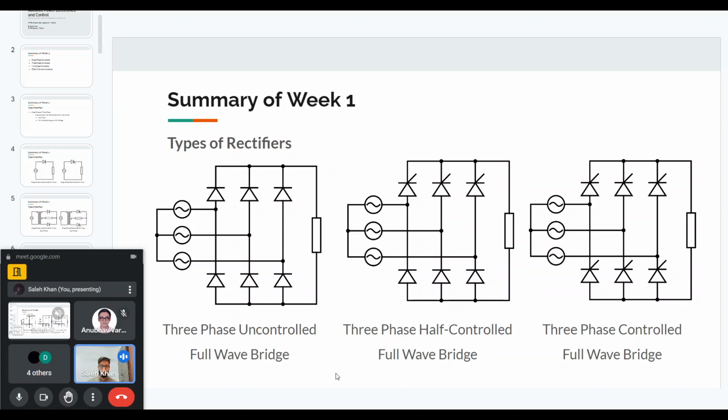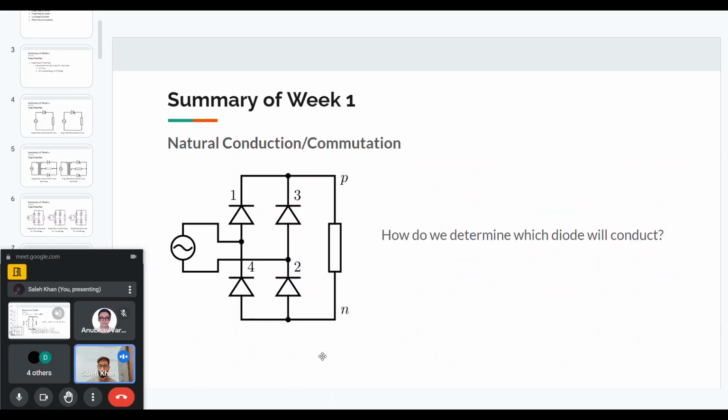And so another converter that was taught was a dual converter, which is just this converter with another of these converters connected on the other side, which allows for a negative current, and therefore we can have 4-quadrant operation. But the basic circuits are only based on these converters that I've shown.